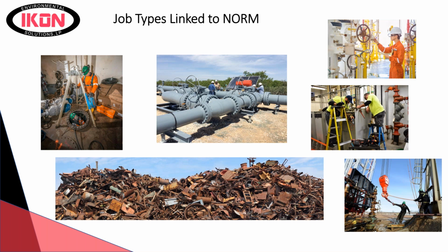And so I don't know what all goes on down at however deep you're drilling, but again, it goes back to the actual, usually it's uranium and thorium, the primordial isotopes that are down there in the formation, and it's getting the radium that's soluble in the produced waters. And I'm sure it has to do with flow, pressure, temperature, and well, and it could also have to do, from what you guys are telling me, with solids in the tank and buildup of solids over time. Concentration of it, just like in your pipelines, your main concentrations are going to be where it collects, mostly in your welds, your filters, and your valves, and that's why a lot of valves.